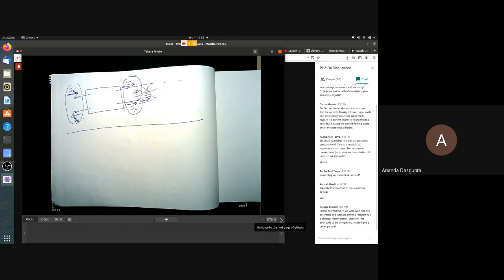We can ensure that the output voltage of a circuit is proportional to the input current somewhere, which is, of course, something you always know, right? And that's what a current to voltage amplifier would be like. There would be a complicated bunch of things inside, but a very simple model of that will be a current control voltage source.